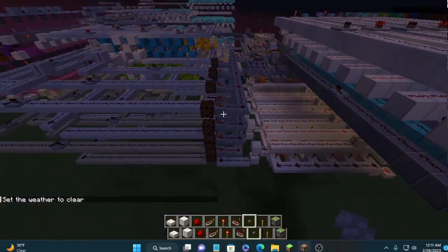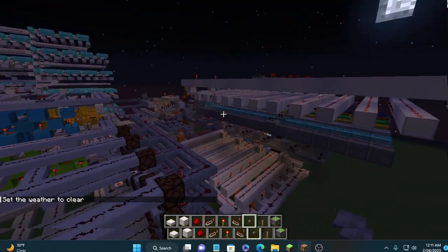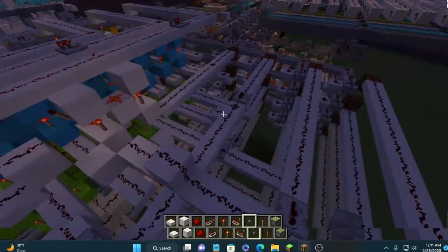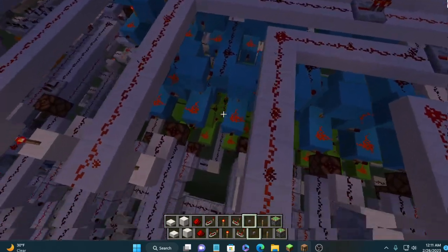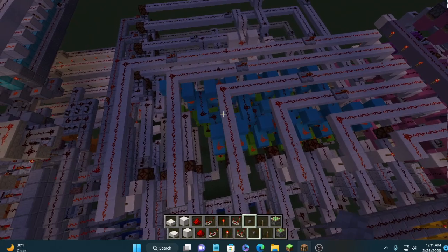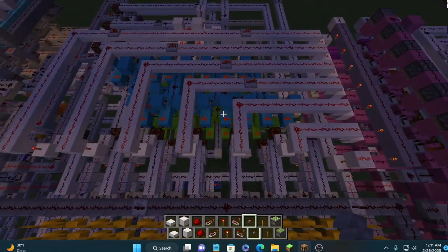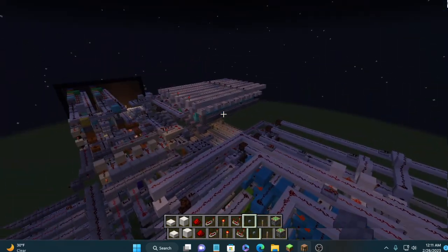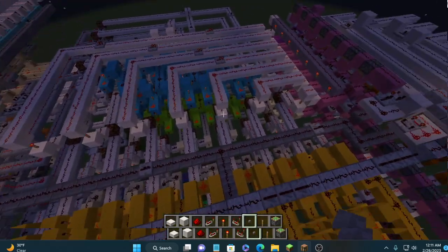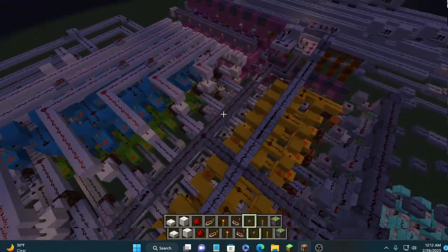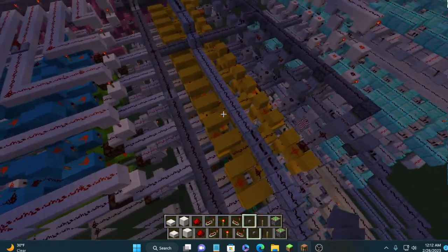So, each one of these repeater RAMs has an according cell up top, and it also goes into what appears to be a ripple carry adder, this blue and lime, but that's not actually a ripple carry adder, that's reverse double dabble or half and dabble algorithm, converting human numbers, as it were, into computer numbers so we can do math with them. Orange here is my main adder and subtractor.